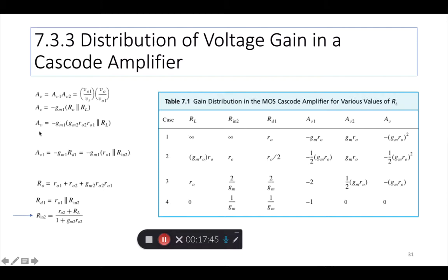Now, so far nothing new. If you want to find the gain only because of the first stage, which is the gain cell transistor only, its gain is given by GM1 and a new term RD1. Another form of this gain is GM1 into a parallel combination of RO1 in parallel with another new resistance Rn2.